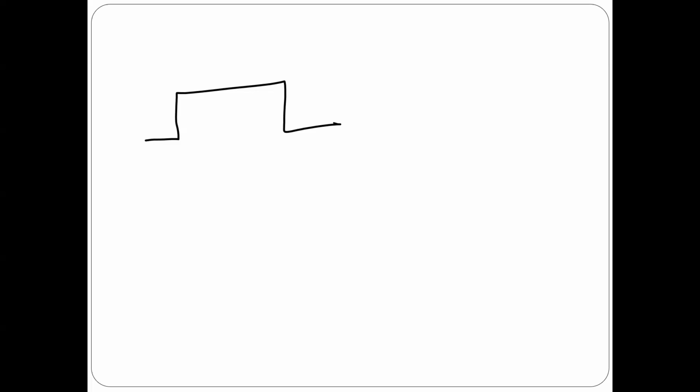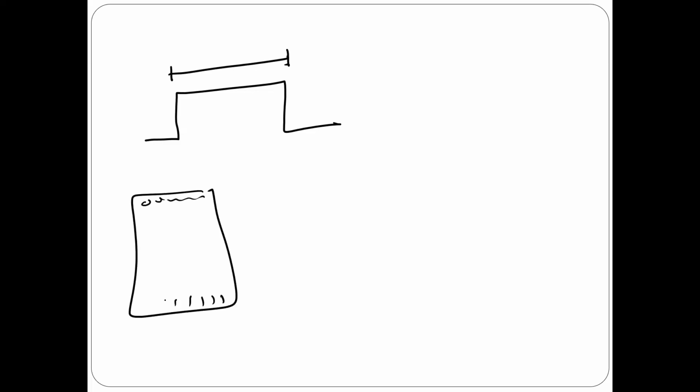For example, I want to measure the time from here to here. How can I do that? Okay. Counter is my friend. Counter is going to help me. How? I'm going to tell you how. Look here in the counter, for example, this counter should count from 0, 0, 0 until 1, 1, 1, 1, 1. Is that okay? Now, I'm going to look here at this time. What was the count here? The count here was 700. And when this one came, what was the count here? It was 750.